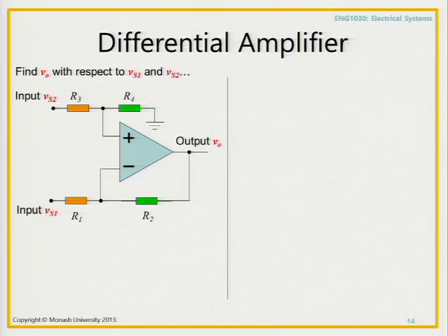So that thing that we're talking about, the differential amplifier. Here is a basic example of one. Have a little look at it. The interesting thing here, firstly, is it in negative feedback? Yes, the system is in negative feedback. Now, the signal, where's the signal coming into? Positive terminal or negative terminal? Both, yeah? So we actually use both terminals of the op amp in a differential amplifier.